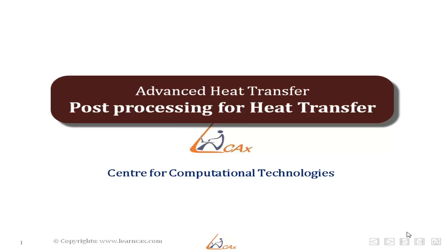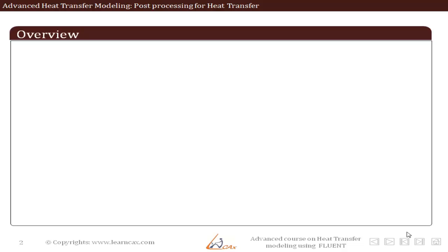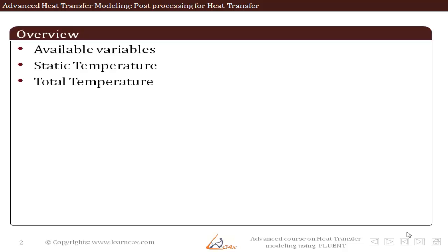In this lecture, we will see various post-processing options available for visualizing results of heat transfer modeling within Fluent software. An overview of this particular course. First, we will see what all variables are available in order to do post-processing or to extract results. We will see how to plot static temperature contour. We will see how to plot total temperature contours.